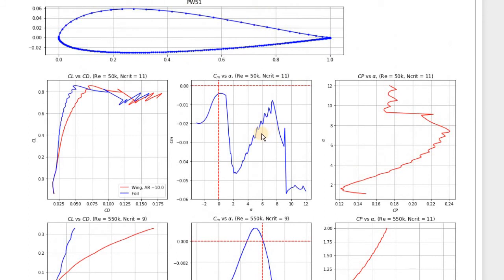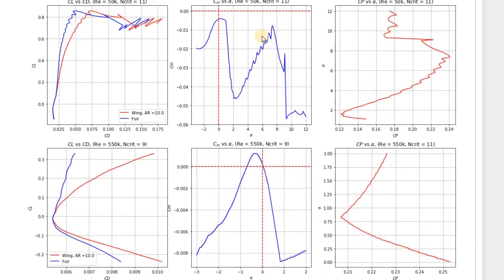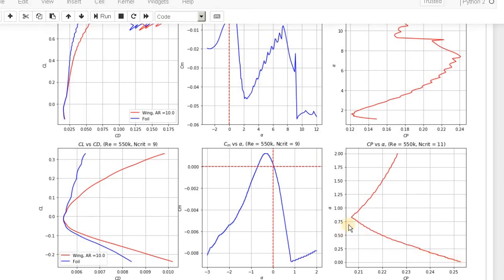So to be 100% sure, you have to move to the one-dimensional space and compute the center of pressure position at the chord at each point. In that case you're going to be more confident, because sometimes this kind of simple rule does not always work. And now please note that this airfoil is unstable at the high Reynolds number. So what can we do about that?